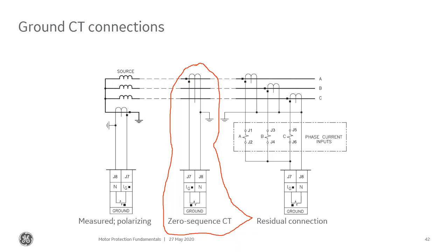That means the magnetic field available to drive a flux into the core of that zero sequence CT is basically the vector sum of the magnetic field of those three phases. So if we have a single phase fault or something like that, we don't really need to worry that much about the CT saturating.